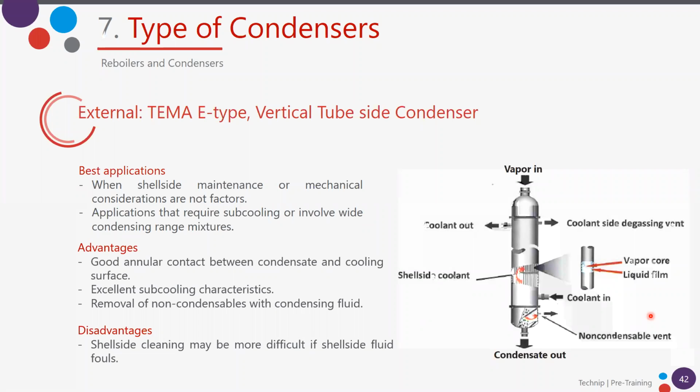Yes, if you take a look at all condensers in industry, you will see that 99.9% of the condensers have a vent that allows taking out the non-condensables. There are always non-condensable vapors, 99.9% of the time.